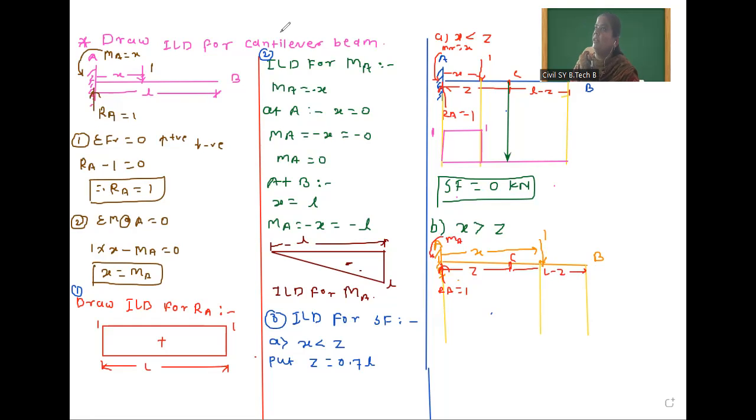When we draw the shear force diagram, at that time we will not consider this moment. So here we will draw the shear force diagram for this. Suppose this is the baseline. Now at a point 1 unit load is there. So up to this we will draw here. From A to the unit load, there is no load, so the diagram is constant up to this. After that, one downward. So here it closes. Now our shear force diagram is over.